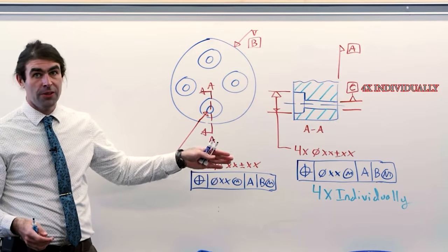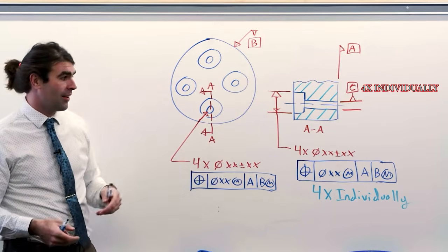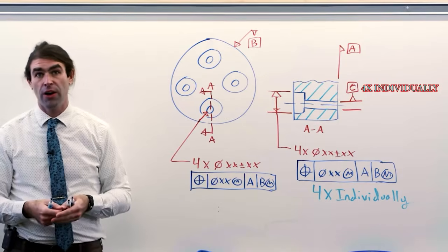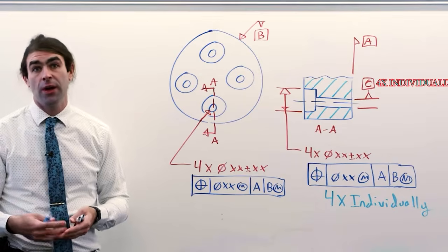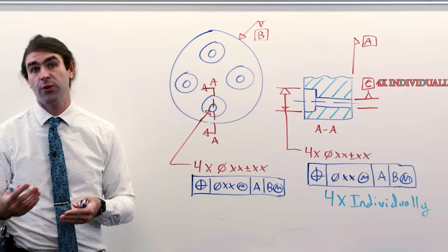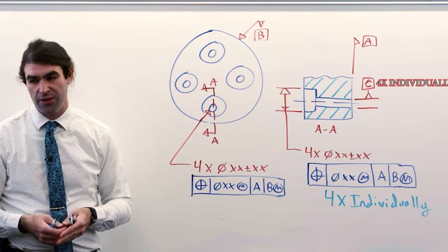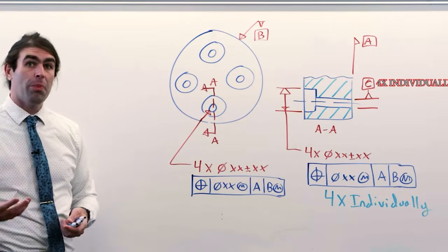For inspection, it can be a little bit more difficult, but it's a tactic that you should be aware of. So this is the other way of doing counterbore holes. These are the 3 ways it shows you in the ASME Y14.5-2009 standard. So let's move on to patterns.